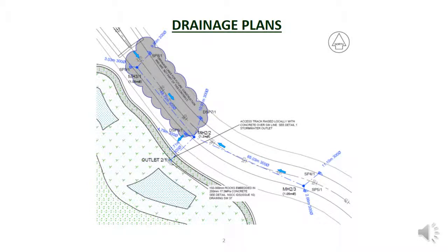The catch pit inlets used here are splay inlets, which are inlets set into the curb rather than grates. So the designer has called the catch pit splay pits as opposed to catch pits and designated them by SP. Note that each splay pit has a number so you can distinguish them. DSP stands for double splay pit, which is two splay pits side by side.